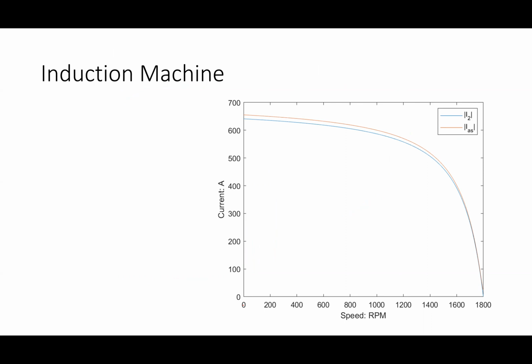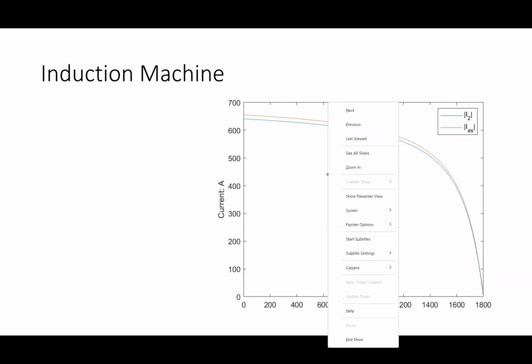And it's a function of speed because one of the resistances is a function of speed. Okay, so if I look at this induction machine, out here at 1800 RPM at full speed, there's very little current. At full, it works out to be about 6 times whatever it is at rated. All right, that's about how this works out.